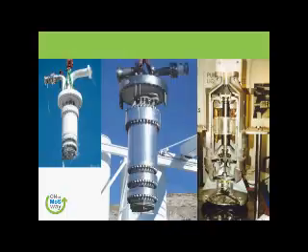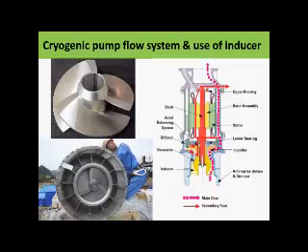the liquid. And can you see on this side there is hardly any clearance in between the casing and the impeller, because the space is less, so that no liquid will flow back. And of course, if we have debris in the tank at the bottom of the tanks, they are going to damage it and the clearance will increase. So this inducer is a very sensitive part of the pump.